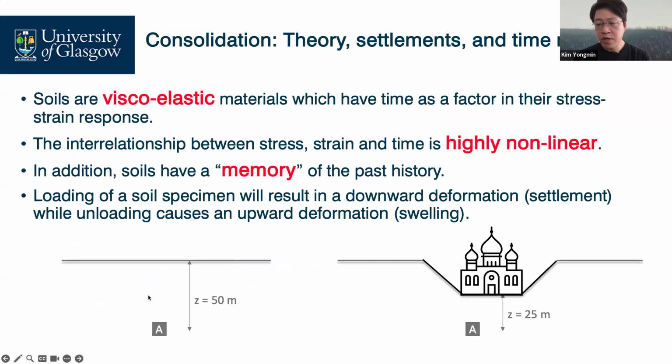That's why we take soil samples from out there and do oedometer tests, and the output is something like the nonlinear compressive curve. We will obtain such curves from the soils because soil memorizes its history, its pressures.